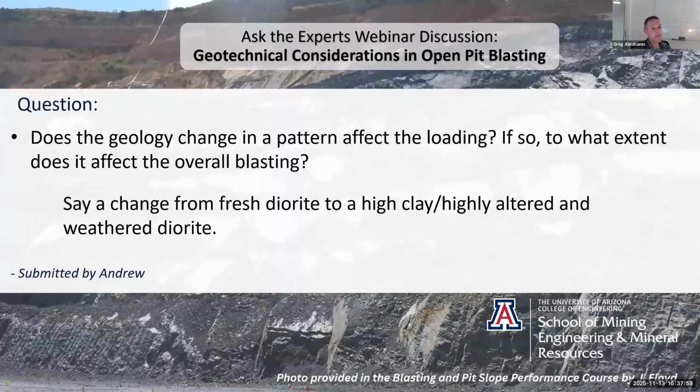And there's some interesting work being done. I've seen it a few places now where you can use the specific energy of the blast drills. It's lots of data that comes from that. I think it might have been an R&D thing through the GC at one point. Anyway, it gives brilliant data on basically the strength of the rock and quality of the rock, and you can even see structures through it.